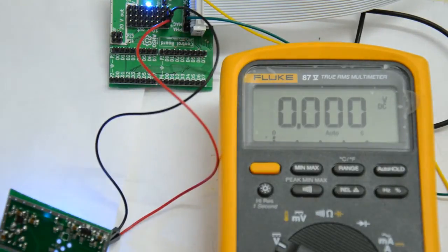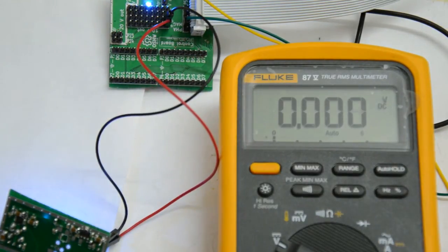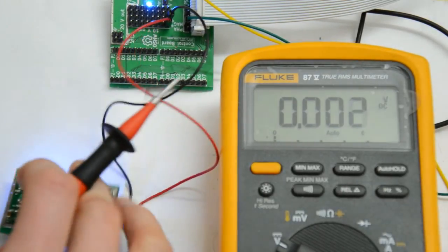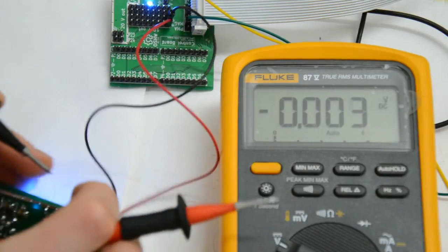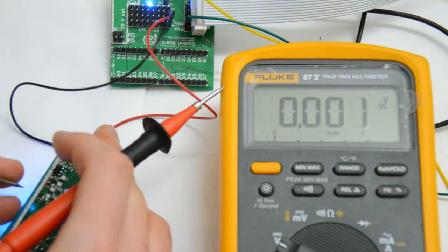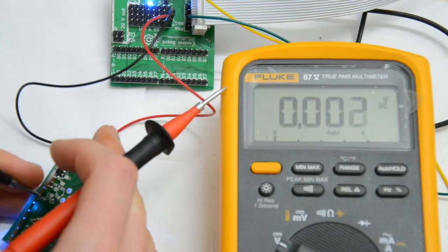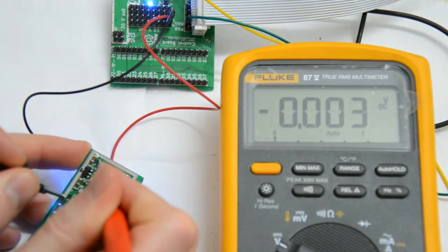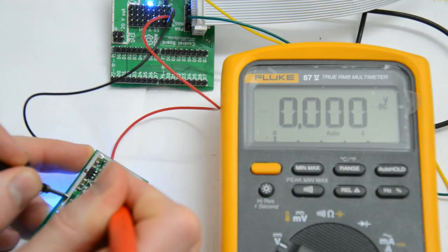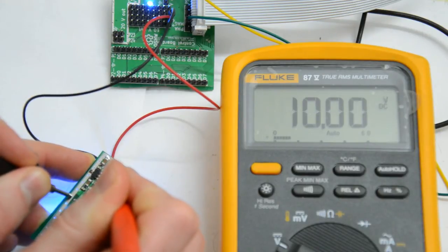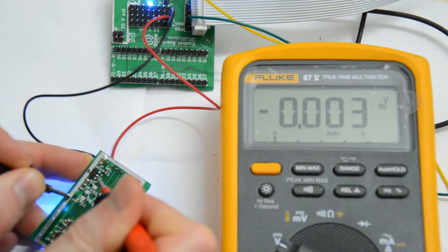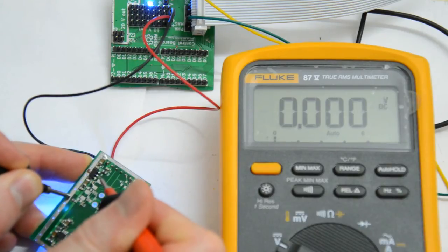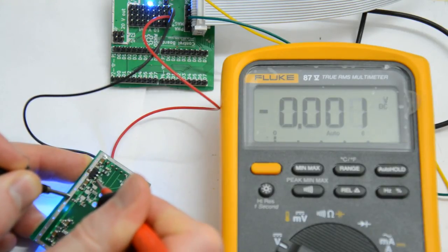Now I'm going to measure a few voltages, and I can imagine that this is a bit difficult on camera, but I'll try my best. So first I'm going to measure the 10 volt supply, and I'll use the fence here as ground, and 10 volts should be here. And I get 10 volts, so that is fine. Then I'm going to measure the regulator output, which should be 5 volts.